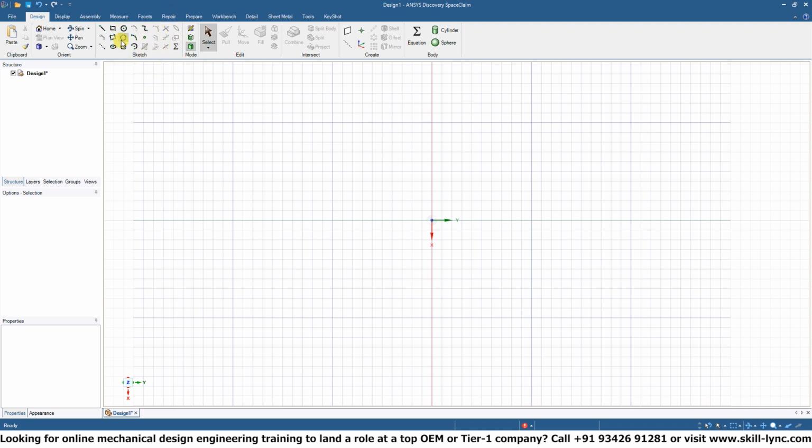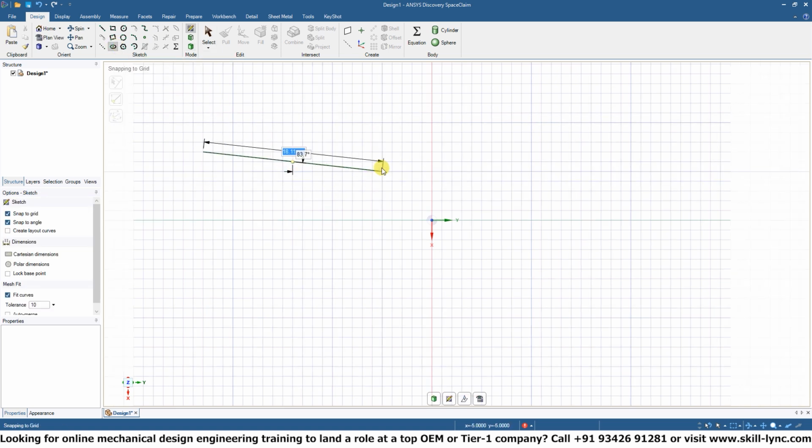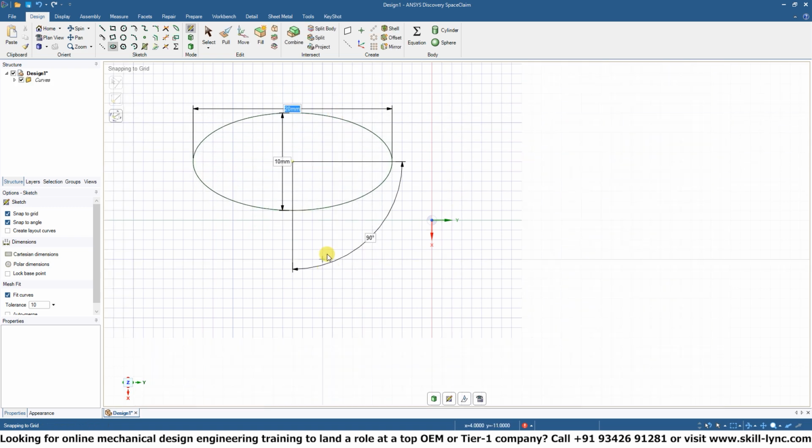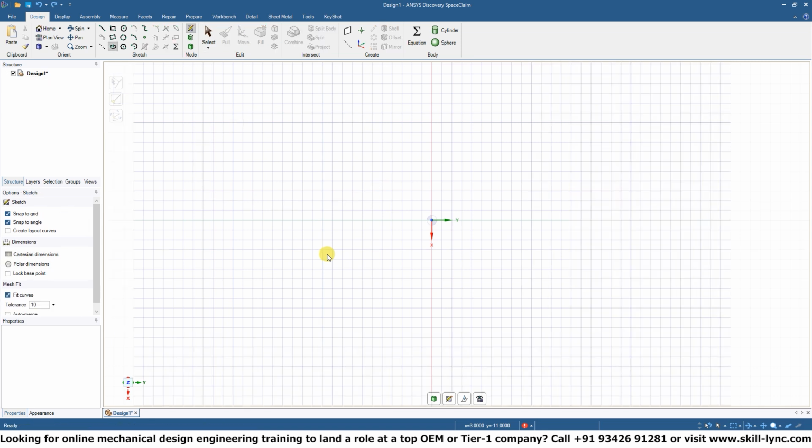There are some that we really didn't cover in the course, but you can practice with them, such as the ellipse tool. So sometimes obviously, or not so obviously, how this works is first you have to select how long you wish the ellipse to be. Let's go over here somewhere close to the center because it defines the center line and the edges from the center. Let's say 20 mil. And then you define how wide you want the ellipse to be, so the thickness over there.